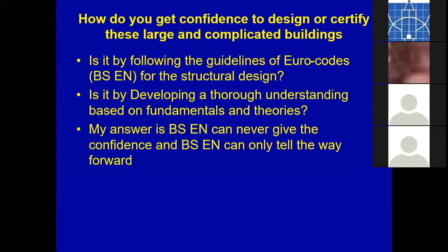And you can use the national annexures. So if you don't have a national annexure for Sri Lanka, the procedure is simple. Simply use the national annexure for UK, because you can get a reasonably good comparison, as they also have fairly warm summers. The summertime temperatures can go up to about 30 degrees. So anything applicable to them can be applicable to us, because ours also, being an island, our average temperatures remain in that range. Because of that reason, you can always make use of the national annexure of the UK if you don't have a properly completed national annexure.